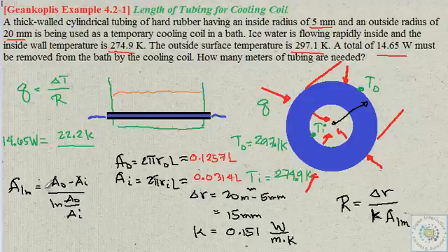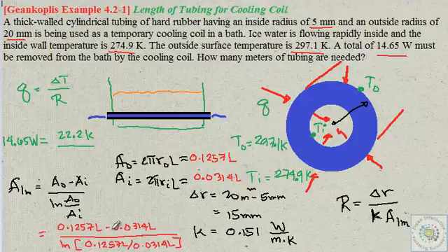Substituting that through here, as you can see, in area O over area I, L will cancel. And putting that in the log mean area equation, with AO minus AI, the L and the L cancel in the denominator. This will then lead to 0.068 L. So the log mean area is simply 0.068 L, which of course has a unit of meters squared because this is an area.